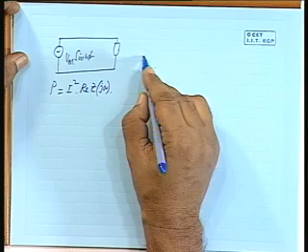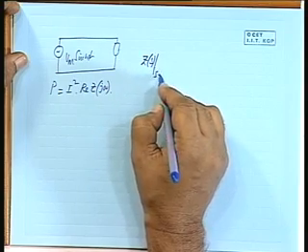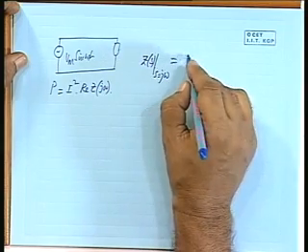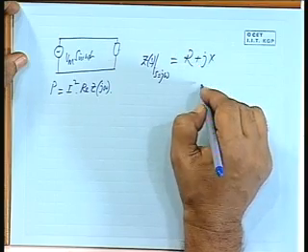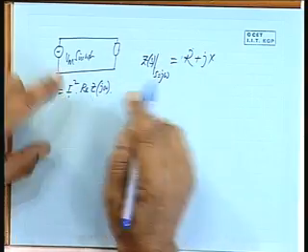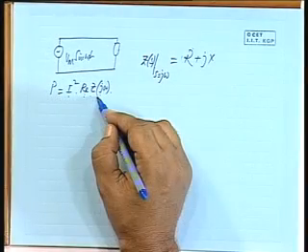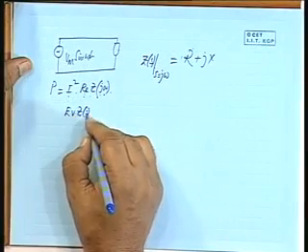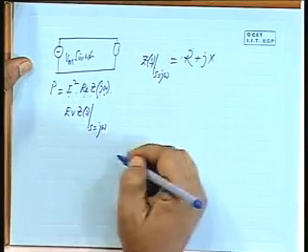That means ZS at S equal to j omega, I can write as some R plus jX. So, it is I square into this R, which will be the power, and that has to be always positive. I square is a positive quantity. That means the real part of this for any omega must be positive. Is it all right? Real part of Z j omega is nothing but even part of ZS evaluated at S equal to j omega.